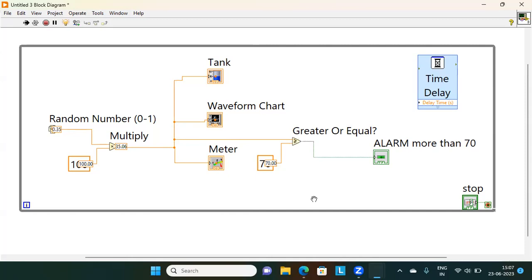So at every point we can see what is the state of our data, how our data is getting modified, how it's flowing. Suppose it doesn't give you any data, but it has written ERR. That means an error is being generated at this module. So LabVIEW engineers highlight this execution and run the program in the block diagram to see the flow of data, and they get to know which particular hardware module is not functioning properly and needs to be replaced or properly checked.